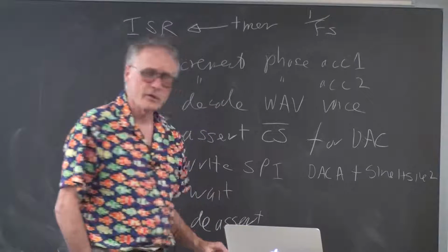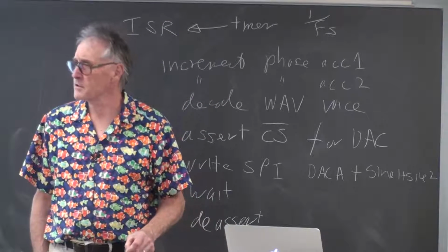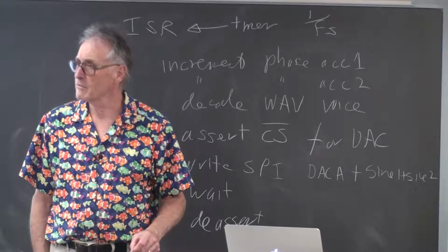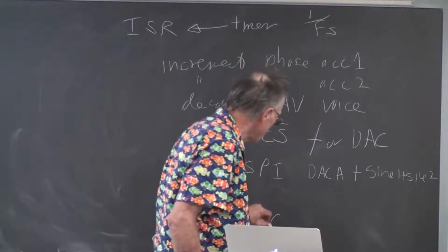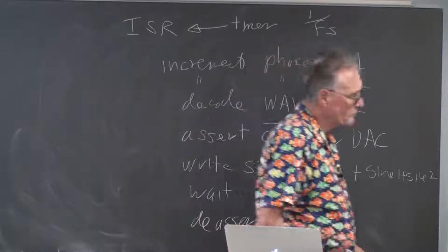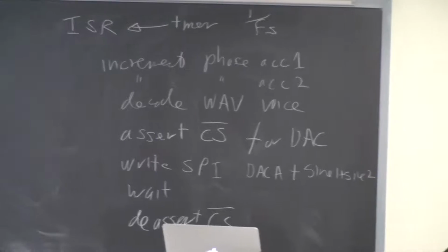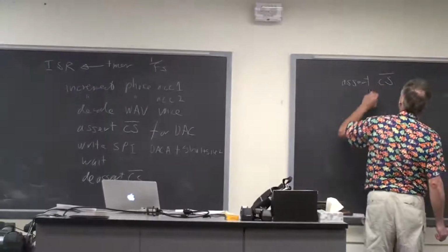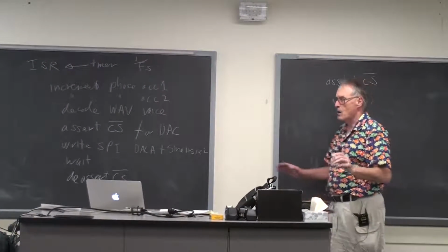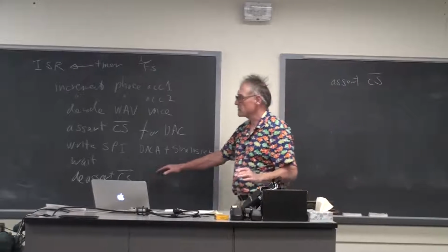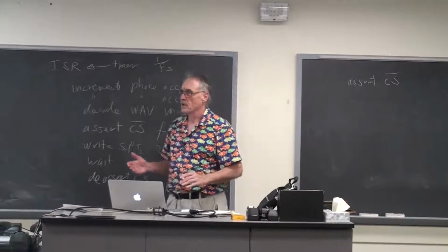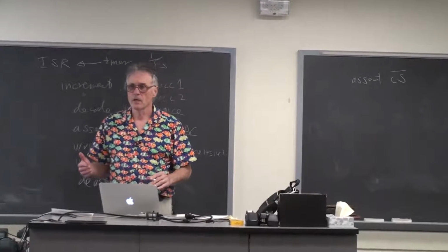Is deassert a word? Unassert? Turn off? I don't know. Deassert chip select. And then immediately again, assert chip select. Say, uh-oh, I'm going to deassert it and then reassert it on the next instruction.